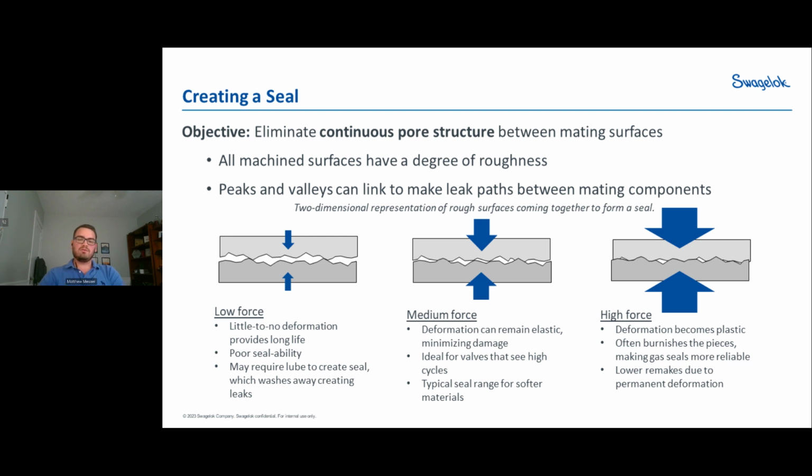Now we'll go to the medium force side. That's usually deformation that's going to remain in the elastic region, so you're minimizing the damage. So you're going to create a higher cycle life. That's really good for valves, like those you'll see with PEEK designs or something like that, so you can minimize the damage that occurs to those materials. So you see that seal range usually for softer materials, like I mentioned, PEEK or PTFE, those kinds of things.